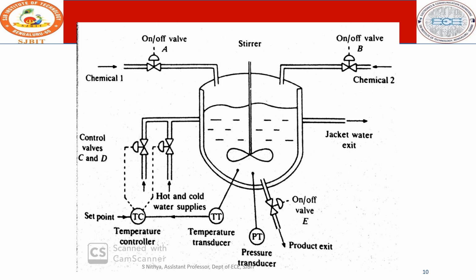And after that we need to set the set points and also the 3-term controller. So the 3-term controller, and then the temperature needs to be monitored always. After that, when the timer indicates that the chemical reaction is done, then open the valve C to feed the cool water, to cool down the materials. Then once that is done, check the temperature. If it has cooled down, then open the valve E to exit the product. So this is the chemical reactor procedure.